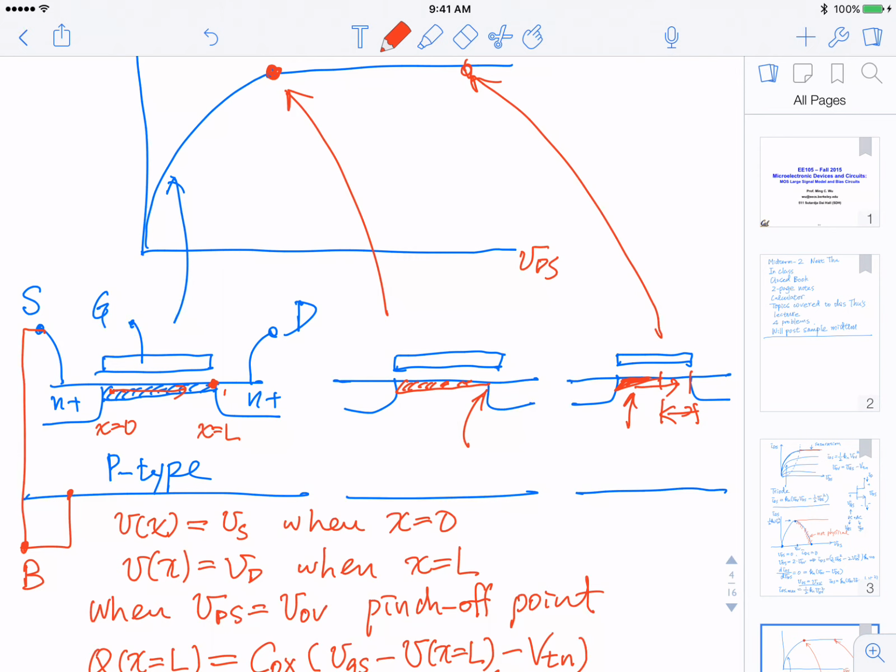And when do we do that? Actually, the threshold voltage depends on the body bias. So sometimes we want to completely shut off one block of a circuit, as in many of the low power circuits, which are quite popular now. We will shift the threshold voltage of an entire block of circuits. We will change their body bias. So it is being used as an additional knob to tune the circuits. For most of our lecture materials, we will assume they are tied to the source.